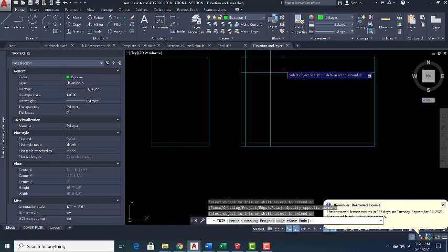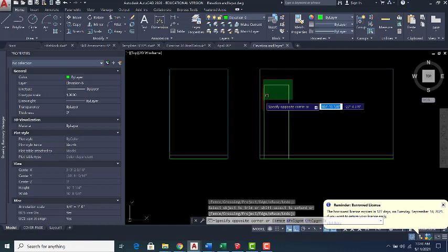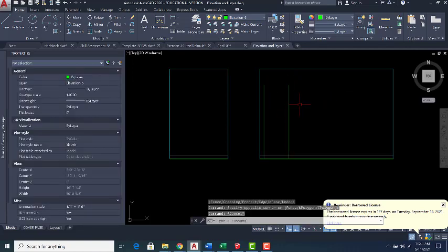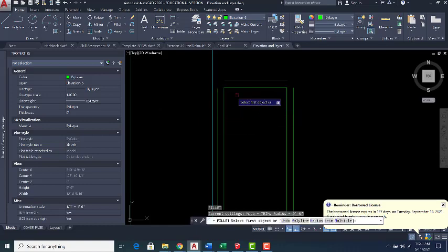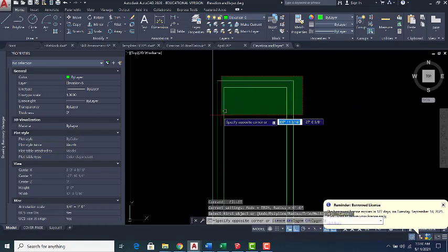I just want to show you guys different ways to do it, but the reason that I don't like this one is that now I am dealing with lines. So if I want to do the frame, I offset this one. See, I end up with extra steps. Then I have to use fillet and close this. And for sure I have to change the layers.